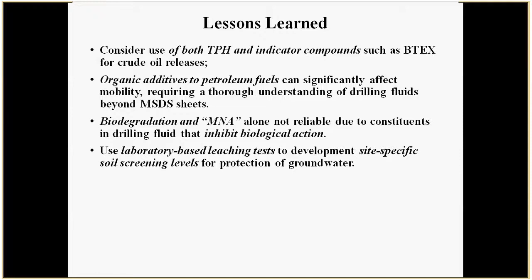Biodegradation and monitored attenuation alone weren't adequate to address contamination at this site. This was interesting because of the additives in the drilling fluid, which were intentionally used to inhibit biological action during drilling and impacts to your oil resources at depth. And they used laboratory-based leaching tests, which is really another direction we need to head to develop site-specific soil screening levels for protection of groundwater.